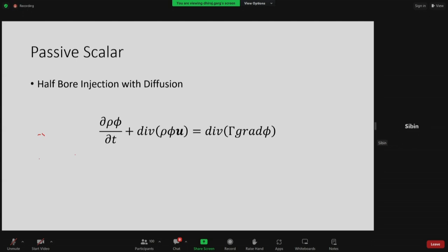So we have to add tracer, like you said, 10 moles per liter, like that. Initially, we have to give a concentration value. So that's what I said. The thing is, if there is no reaction, and there is no non-linear term in terms of, let's say, diffusion, so phi equal to 1 is a good way to overcome the issue of absolute values of concentration.